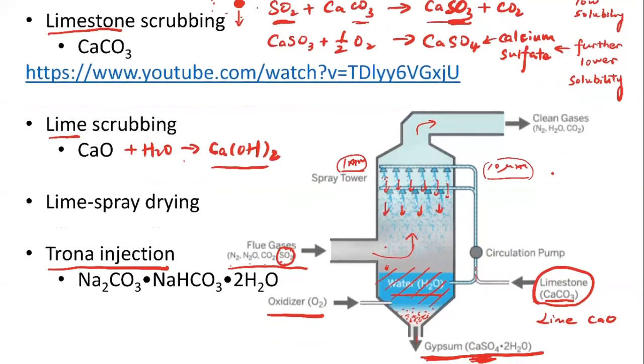And then the other thing that's happening is once we spray these droplets down, while they're settling down, they're also evaporating, right? Basically we can design this system so that before they settle down onto the bottom, they're small enough that they can get carried by the flue gas and then exit from this scrubber here. So we're not forming any water solution anymore.